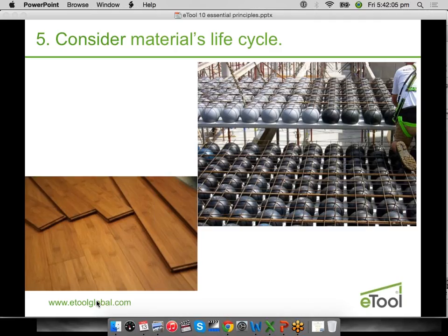For example, with this multi-residential, they use bubble deck to reduce the amount of concrete, and also they get more span. So they're not only reducing the amount of concrete, but they're reducing the structural elements. So they're having less steel, less concrete, because they can have a longer span with the bubble deck slab. So it's changing the structural project. Yeah. What's it called? Bubble deck. Interesting product. Yeah.